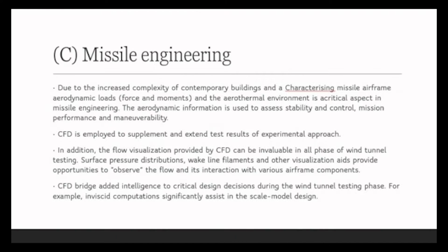Due to the increased complexity of contemporary missile designs, characterizing missile airframe aerodynamic loads, forces and moments, and the aerothermal environment is a critical aspect in missile engineering. The aerodynamic information is used to assess stability and control, mission performance, and maneuverability. CFD is employed to supplement and extend the test results of the experimental approach.